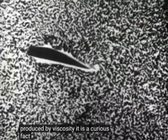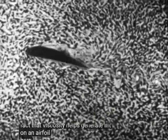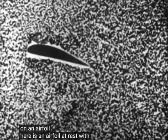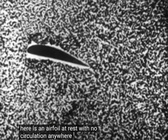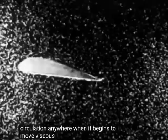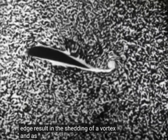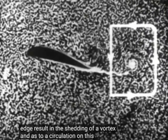It is a curious fact that viscosity helps generate lift on an airfoil. Here is an airfoil at rest, with no circulation anywhere. When it begins to move, viscous effects near the trailing edge result in the shedding of a vortex, and thus to a circulation on this curve.